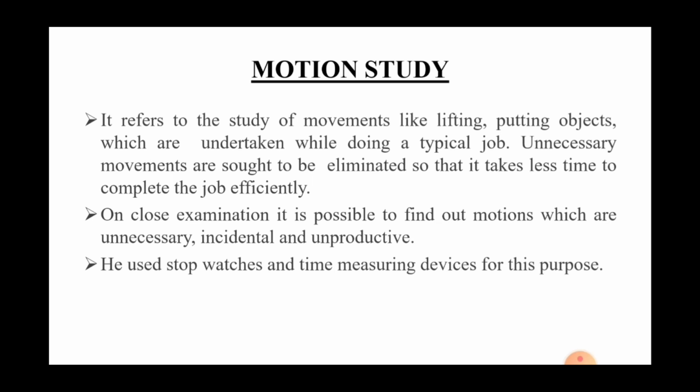The principles of motion study were designed by Gilbreth. He provided different rules to be followed for use of the human body, arrangement of the workplace and material handling, or design of tools and equipment. Like two hands should begin and end their motion at the same time, idle at the same time, momentum, smooth continuous motions, gravity feed bins, drop delivers, etc.